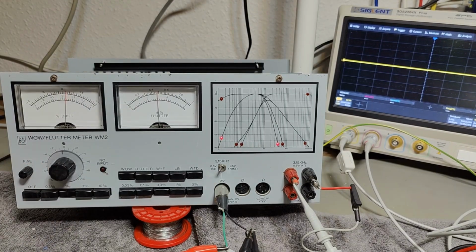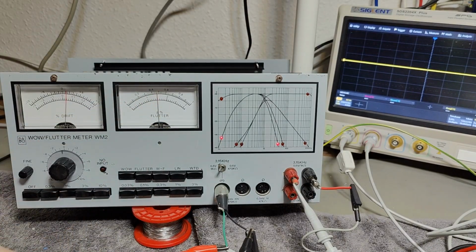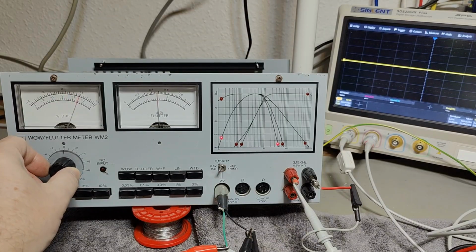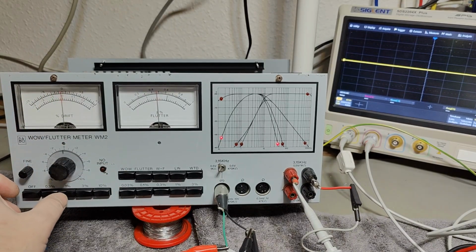Interesting. I can, of course, add a little bit of FM modulation to my 3.15 using my signal generator. So this is what I'm doing here. So we got 5 hertz of FM frequency, and we got 5 hertz of frequency deviation. And that is why you see this. You can actually see that it's moving a little bit. And I can trim this back to 0. But everything is a little bit nervous right now, and it is going.